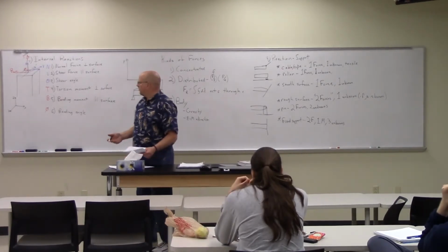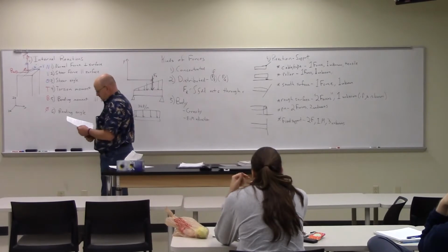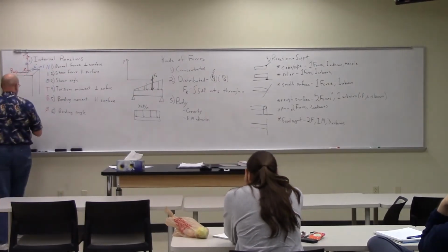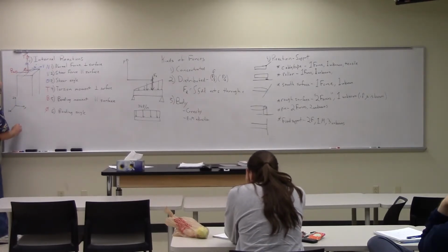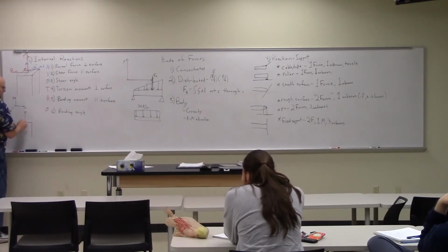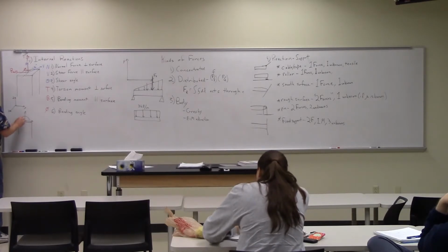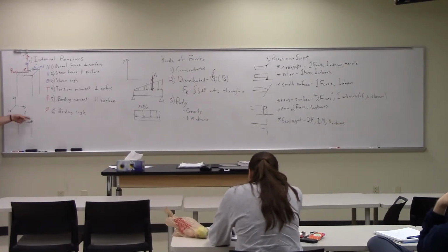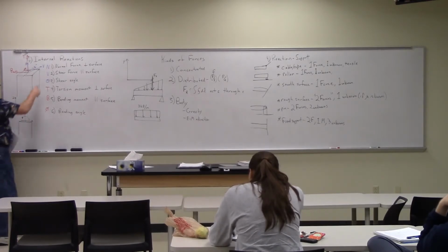And then if we have a two-dimensional system instead of a three-dimensional system, now we're just going to take this thing and look at it two-dimensionally, so we don't allow for a third dimension into the board. Now I can still have a normal force, I can still have a shear force, and I can still have a moment, but the only moment that's left is the z, right? We have the x and y forces, and the moment about z. So in this case, the x and y are n and v. There is no theta.